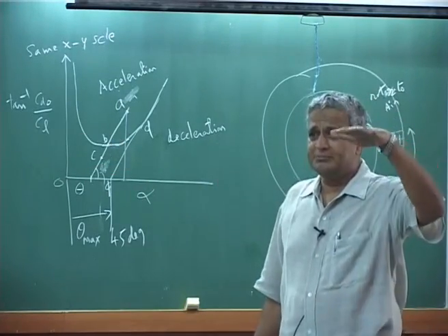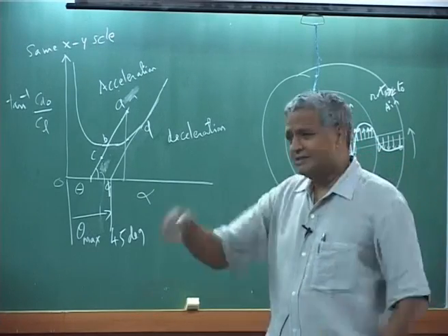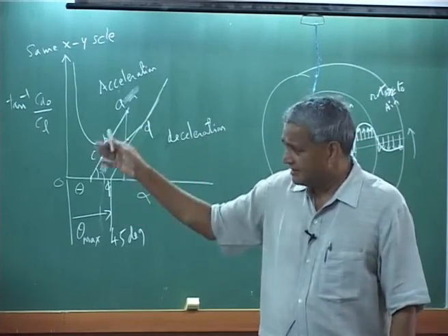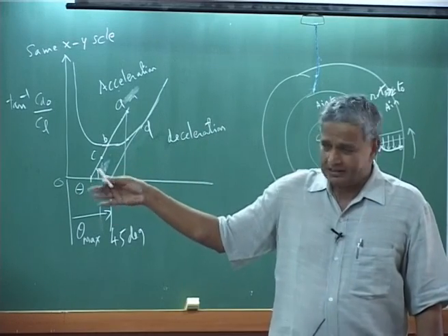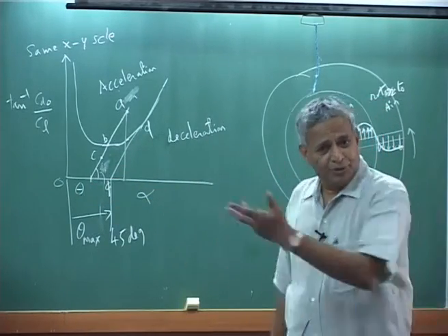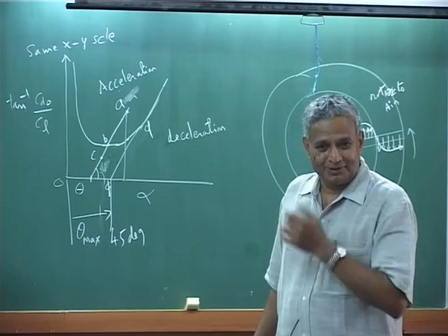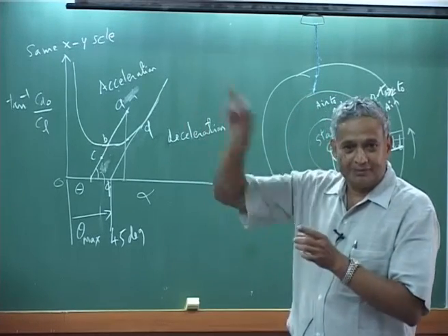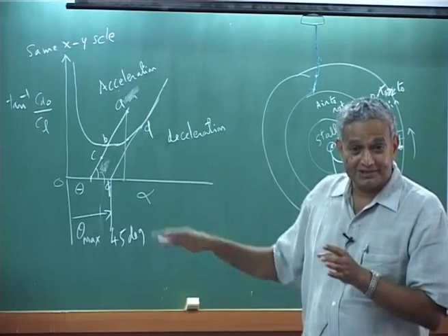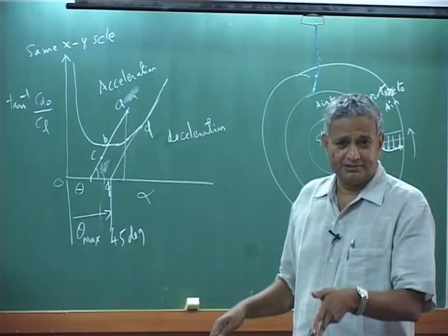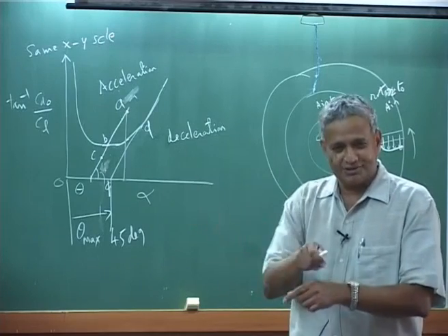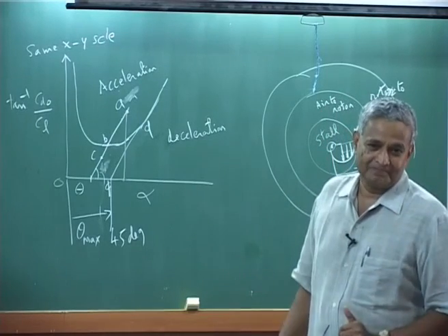You say if I design at this velocity, this is my inflow, calculate every section what is the drag force, integrate over the whole thing, you will know what is the power. So they will keep on drawing the power curve with respect to climb and descent. Wherever it meets 0 or you extrapolate to 0, that is the descent velocity, that is all.